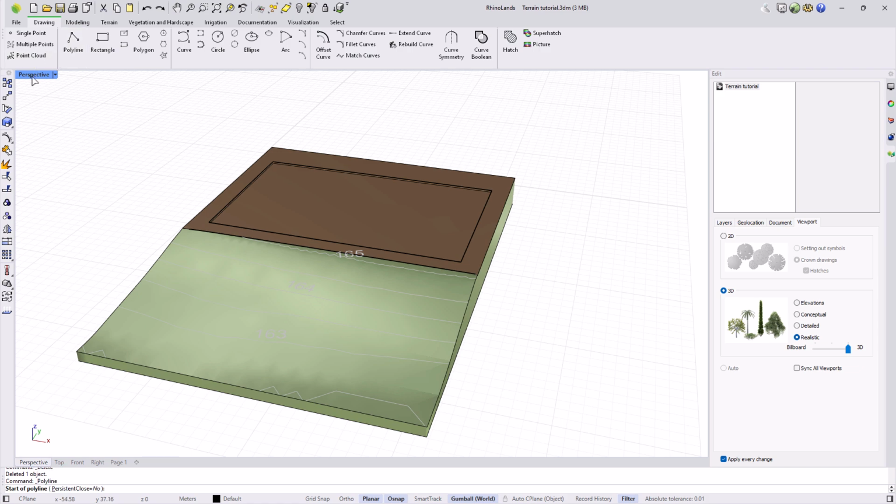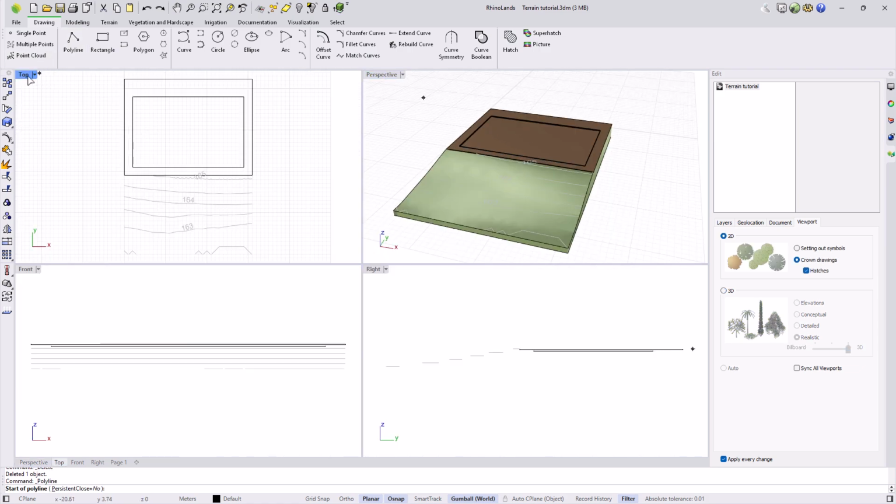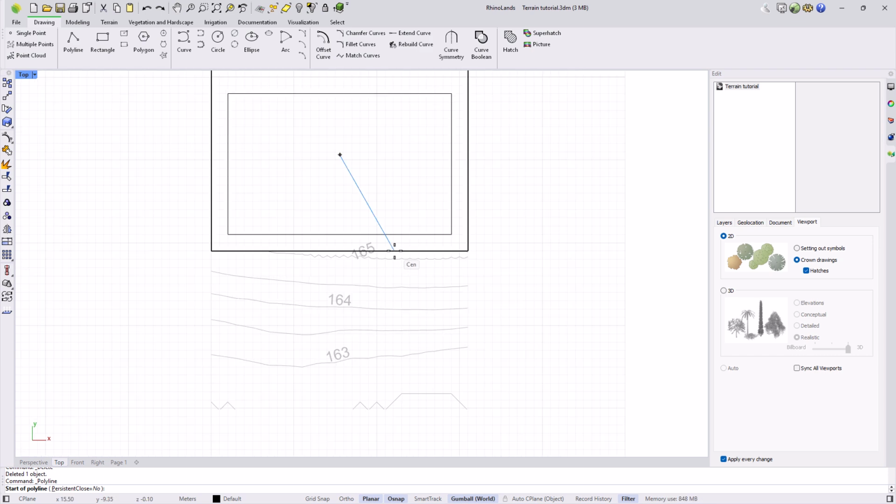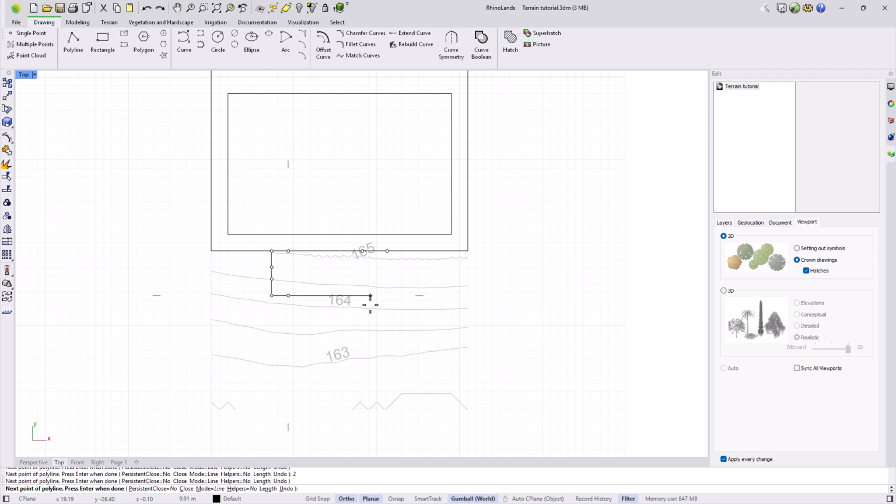First, I'm going to create a polyline that follows the entire path of the ramp. I position myself in the plan view and start from a point. Maintaining orthogonality, I create the first section, which will be a flat stretch of 3 meters, followed by the first sloped section. I'm going to give it a length of 9 meters and another section of 2, which will be the width of the ramp. I continue with a 90-degree turn and a value of 2 plus 1.4 plus another 2 meters. I come back with 2 more, followed by 7 ramps and 2 more.